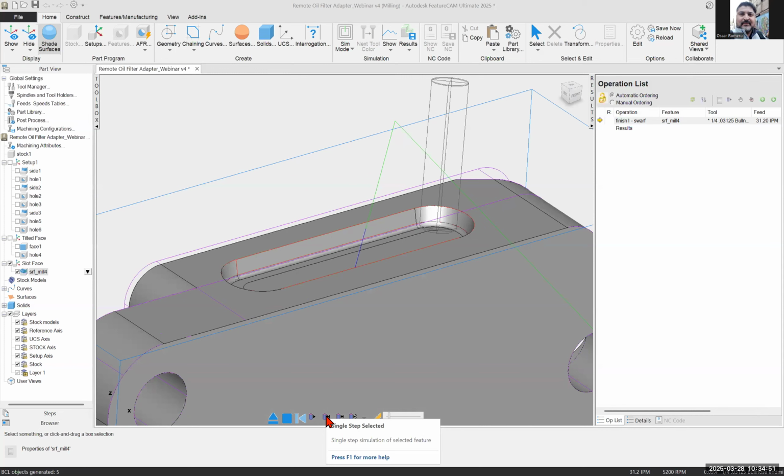We can actually go in there and machine surface that with a ball mill from the top all the way to the bottom, but obviously that's going to take many passes. It could leave some scalloping. And of course, we may want a nice finish on this. This is going to take the least amount of time. So applying a swarf, automatic swarf style toolpath here is, for me, the best option.